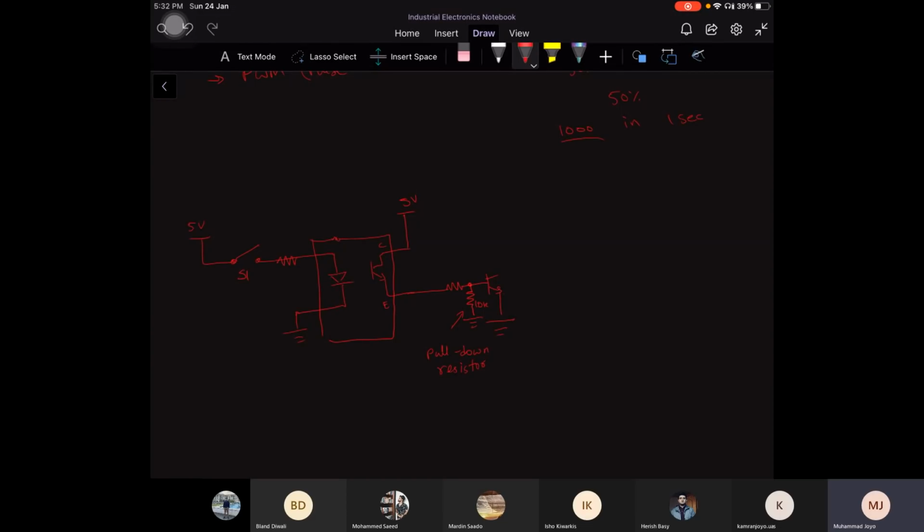In technical terms, it will make sure that when your optocoupler is providing nothing, 0 volt, I mean the transistor is not turned on, this pull down resistor will make sure that 0 volt is going to your base. So in any case your transistor is not turned on until the optocoupler turns on the transistor inside it. Okay, let's connect a motor to it.